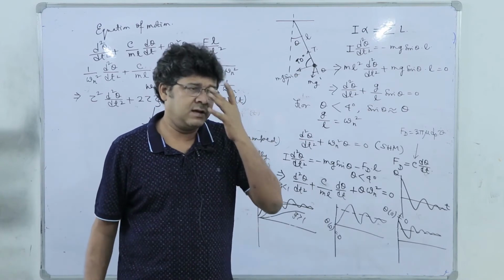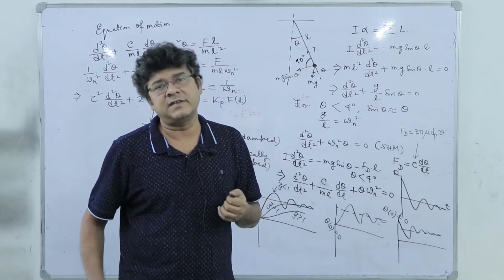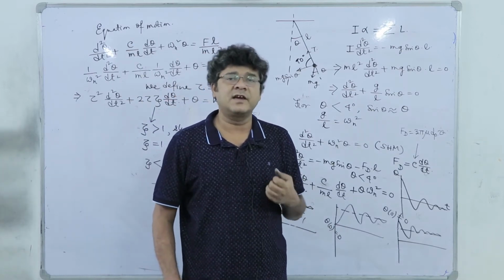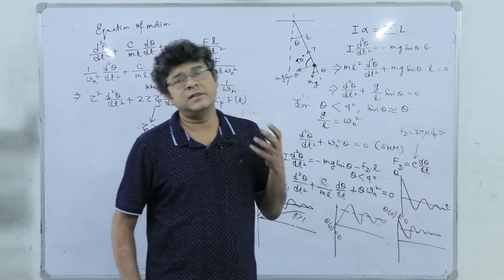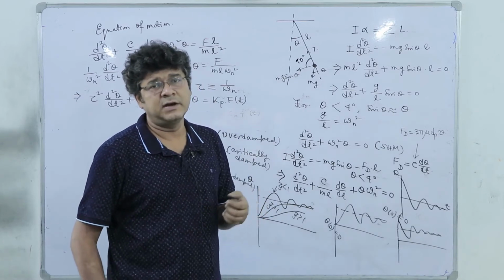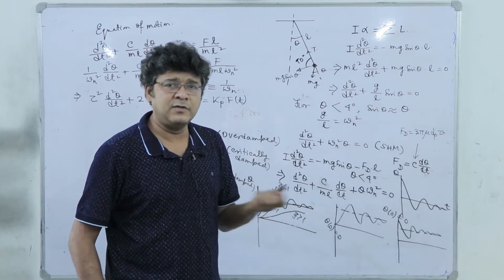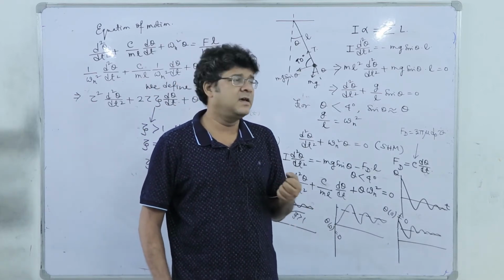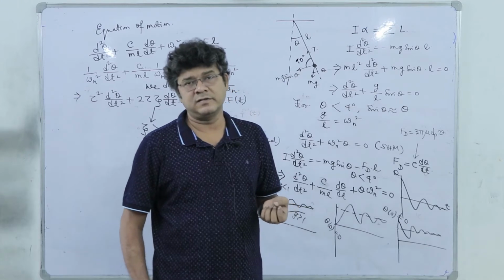So, we will see later in our discussion regarding the origin of the second order system that if we connect two first order systems in series, it becomes a second order system, right. So, the same mercury in glass thermometer, based on the relative values of the resistance and capacitance of glass and mercury respectively, can behave also as a second order system.